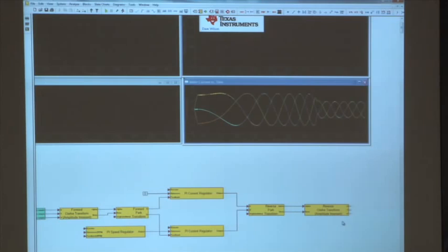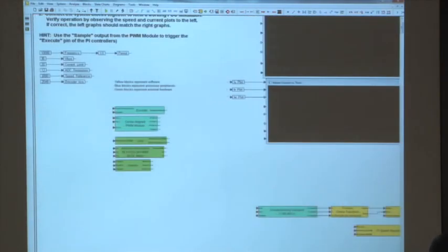Well, okay, but those only exist as 0 to 1 signals so far. I want to run them first through a PWM module. So I'm going to take those values and drop them into my PWM module. So go over here and find the center-aligned PWM module.